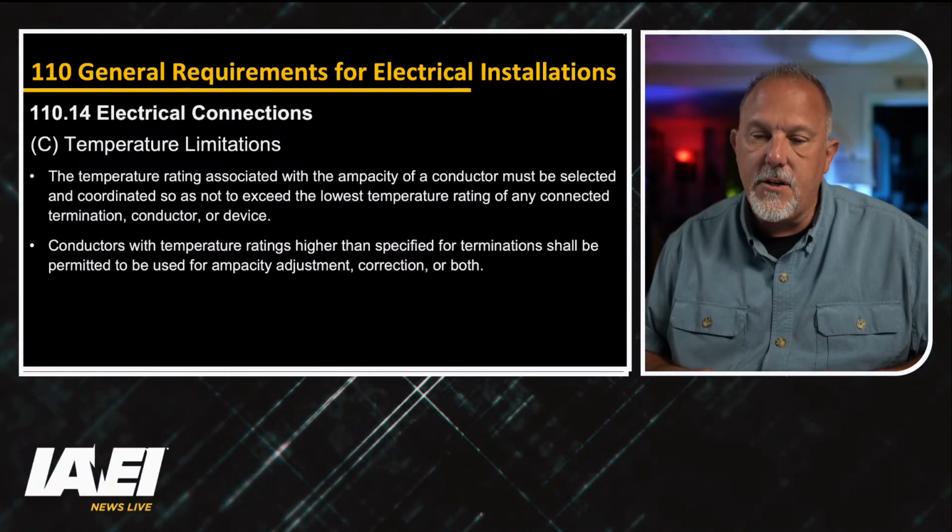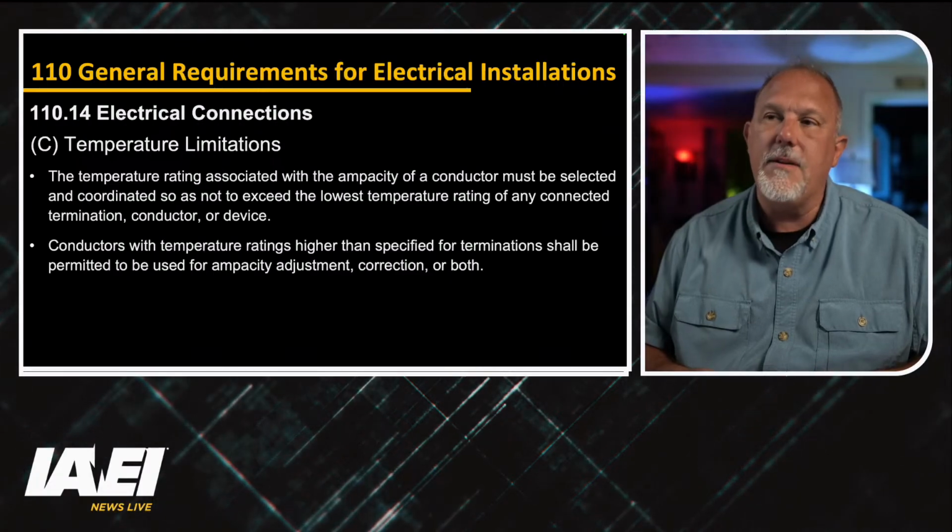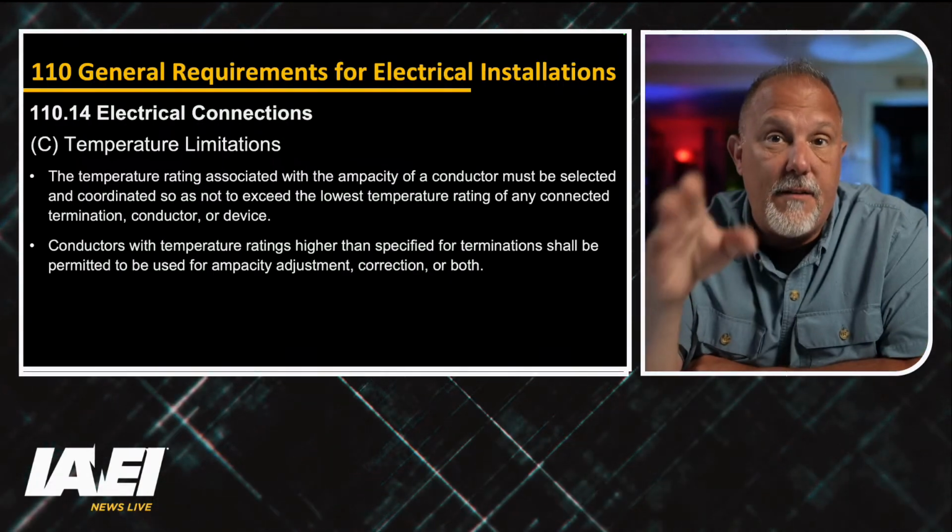And the ampacity of the circuit shall be limited or adjusted by the overcurrent. No, so here's my suggestion there, Felix. My suggestion is we worry about the overcurrent protection later. Remember, the equipment 75 degree C does not mean you always have an overcurrent protective device. My 75 degree C could be a terminal block, or it could be a transformer with no overcurrent protective devices in it. So just because I have the 75 degree C and I'm limiting it based upon the equipment is not necessarily because of the overcurrent device.